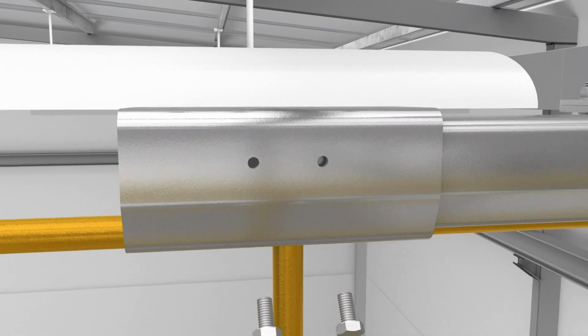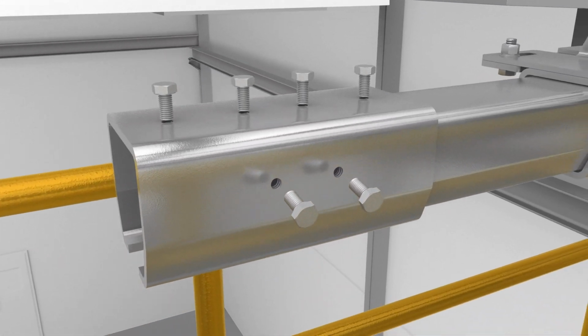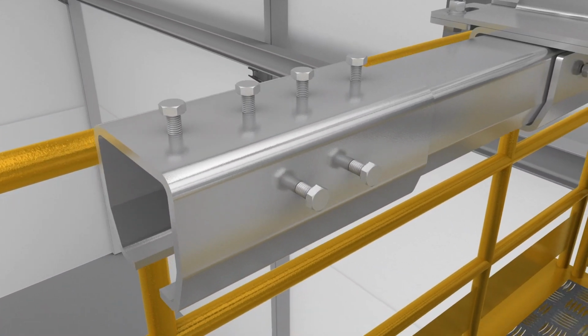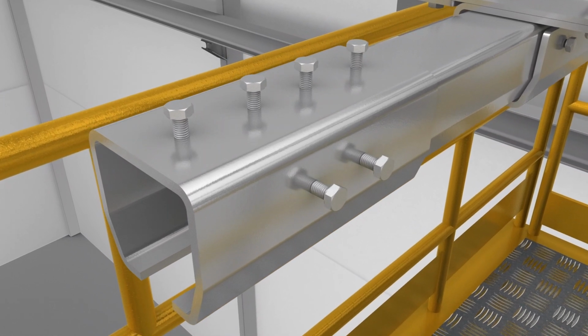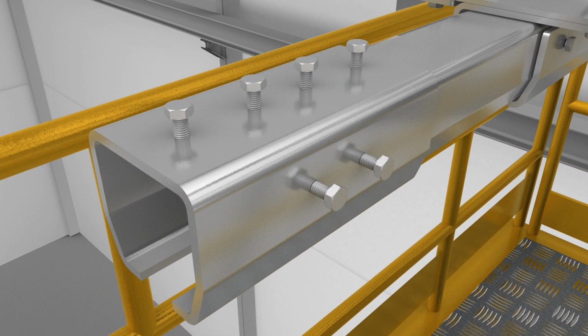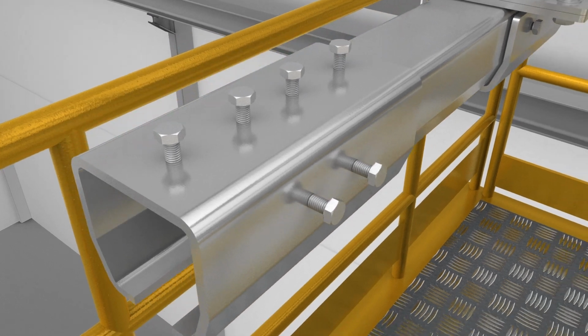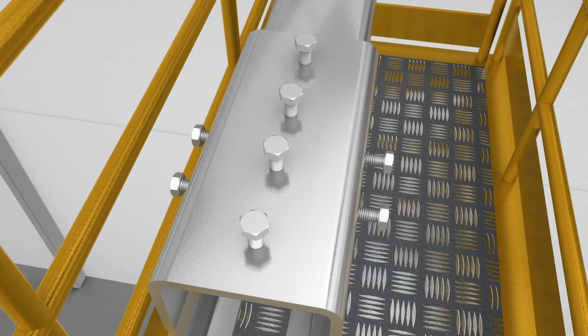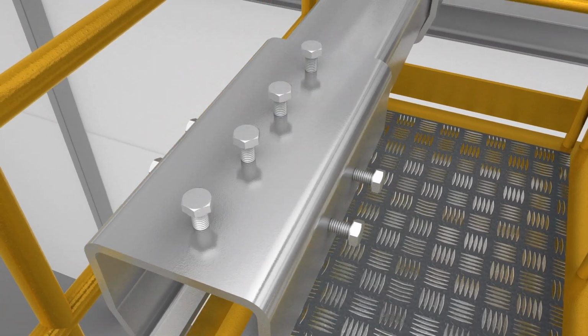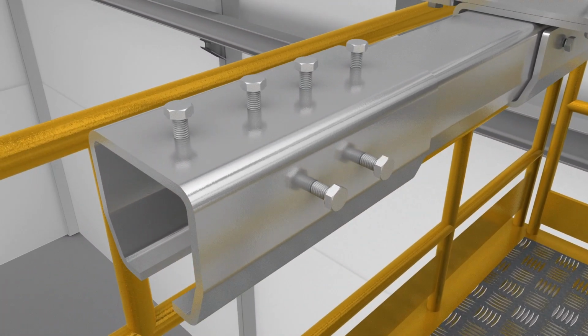Insert a total of 8 M10 20mm pinch bolts into the threaded holes that are located on both the sides and the top of the rail splice. To secure the rail splice in position, carefully tighten the 4 pinch bolts that are located on the fixed section of rigid rail only. Care should be taken to ensure the 4 pinch bolts are only tightened sufficiently to pinch the rigid rail during this step.